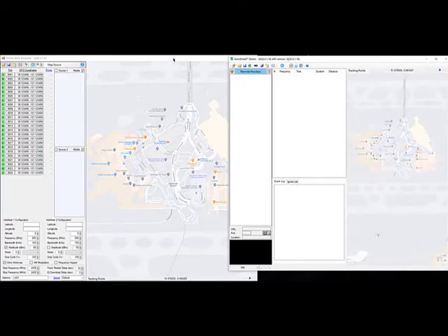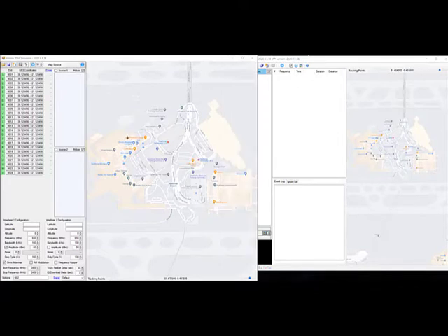The RSM probe positions are positioned on the map by right-clicking and then copying the GPS coordinates and pasting in the GPS coordinates column on the left. We can also measure the distance between one probe and another by right-clicking and moving your mouse to trace to another position. In the bottom you can see a meter determination. And then place a probe in that second position.